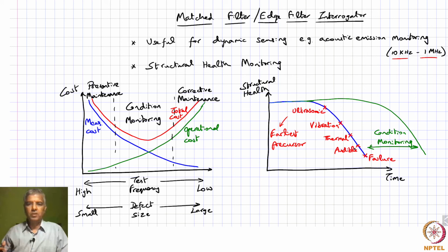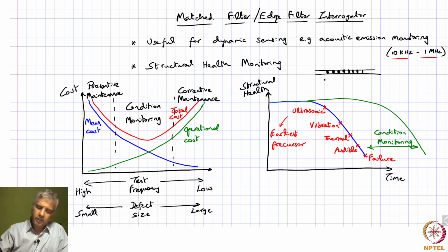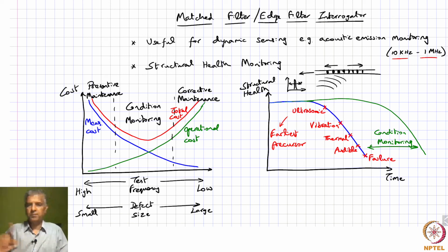Now, clearly, when we talk about ultrasonic waves, the fiber Bragg grating itself, this is just the periodic structure, and we are subjecting it to some ultrasonic waves that are hitting this, and based on that it will basically stretch and compress. So according to the frequency of the waves, you are going to have a back reflected wavelength, which is going to move back and forth in wavelength corresponding to the waves that the grating is exposed to, right?